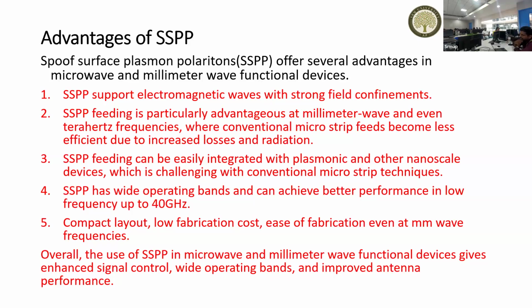And the third one is that SSPP feeding can be easily integrated with plasmonics and other nanoscale devices, which is not possible with microstrip feeding techniques. We can't integrate them like that. And one more thing, it offers wide operational bandwidth, which is also an important advantage. And we can design compact layouts, fabrication is very easy, and the fabrication cost is low.